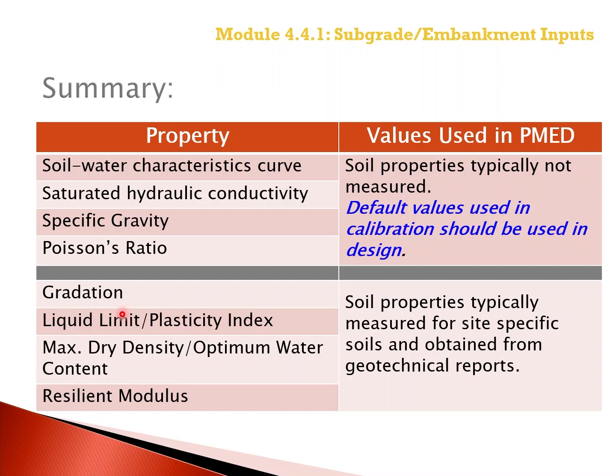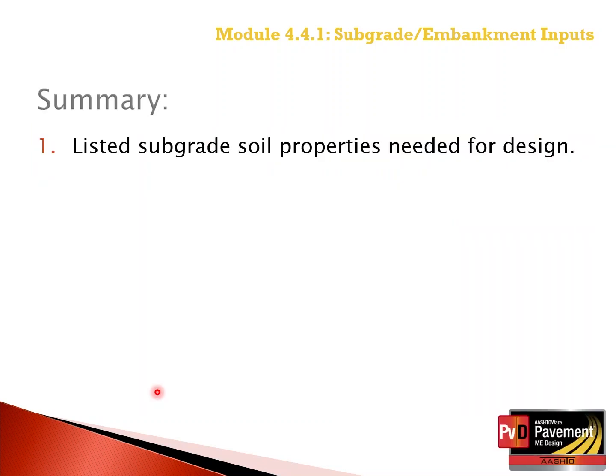Gradation, liquid limit, plasticity index, the maximum dry density, optimum water content, or the dry density and water content associated with the resilient modulus determined by the user are normally entered and are project specific and or design segment specific, and come from geotechnical reports.